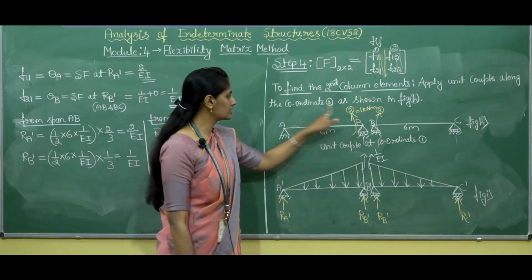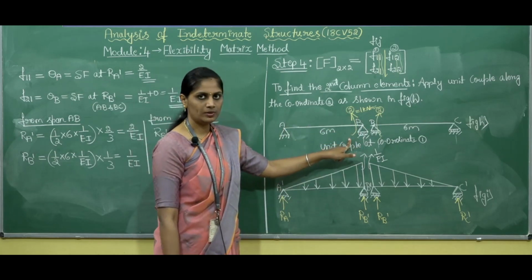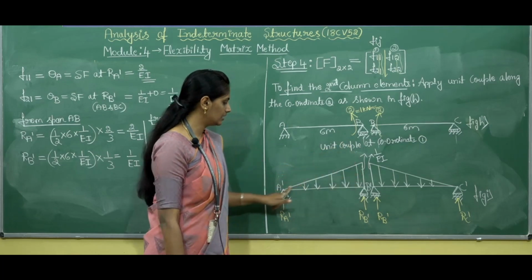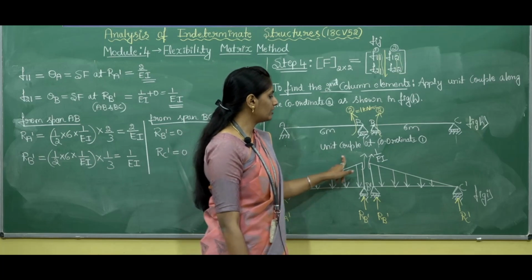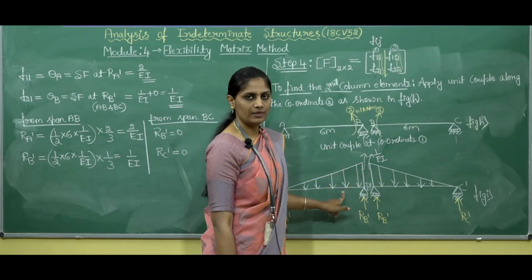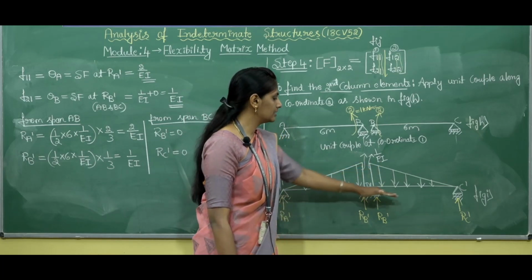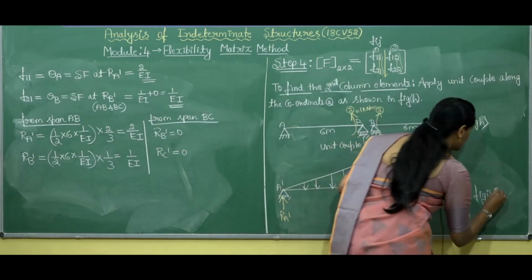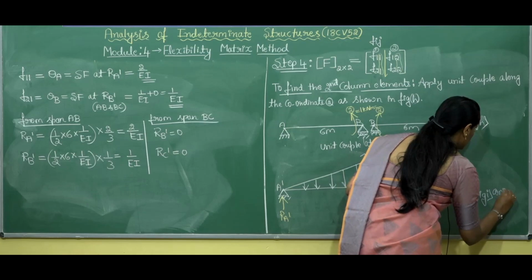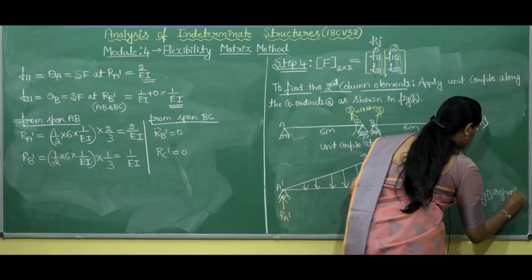Clear? So for this kind of loading arrangement, we get the bending moment diagram in the right angle triangle pattern. So the bending moment value divided by EI gives the M by EI diagram, and this forms the conjugate beam. Therefore here figure I is the conjugate beam.